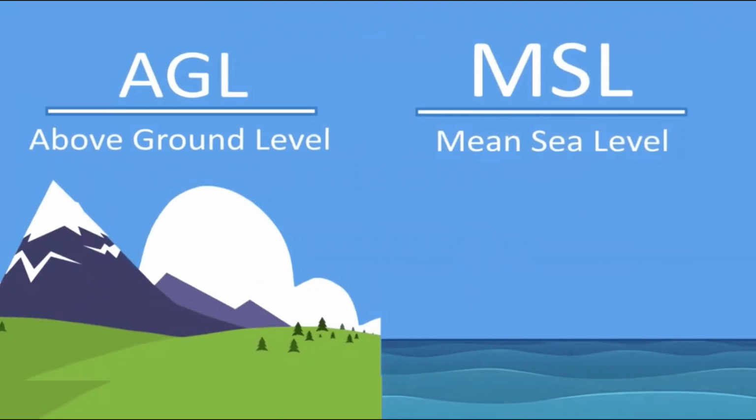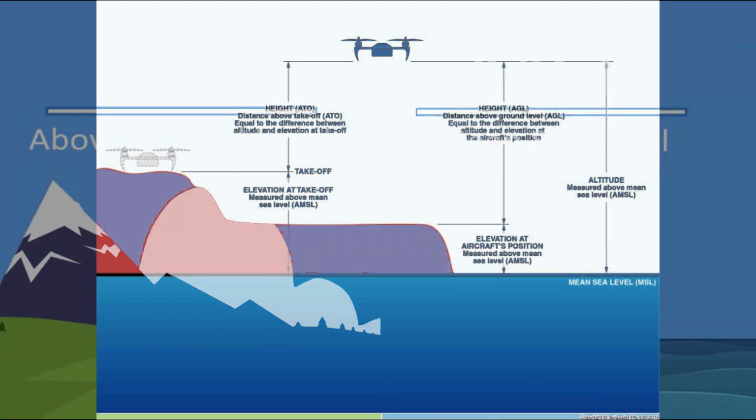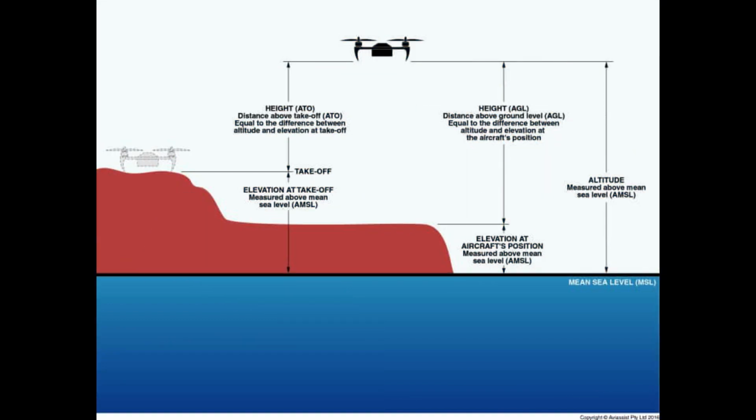Altitude above ground, QFE. A local altimeter setting equivalent to the barometric pressure measured at an airport altimeter datum, usually signifying the approach end of the runway, is in use. At the airport altimeter datum, an altimeter set to QFE indicates zero altitude. If required to use QFE altimetry, altimeters are set to QFE while operating at or below the transition altitude and below the transition level. On the airport, the altimeter will read 0 feet.